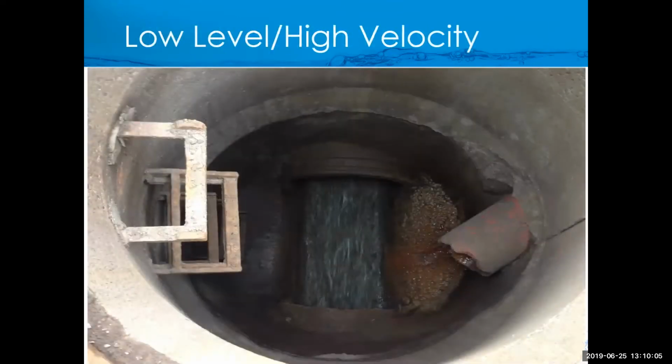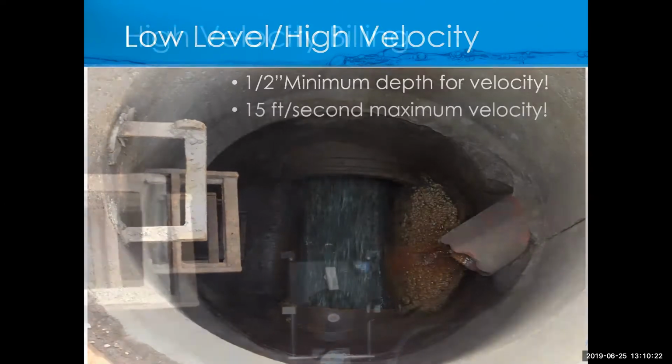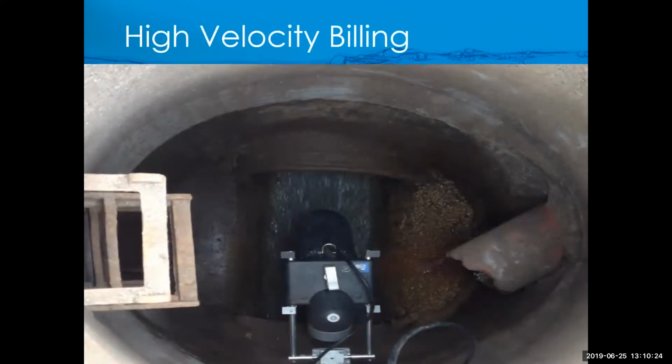Okay, so here's a shot I thought looked pretty good. This is a low-level, high-velocity application up in Minnesota. Their depth here was less than 1 inch, so they couldn't put a standard AV sensor in and get good results. The laser spec is a 1/2 inch for velocity, and we will read up to 15 feet per second. This shot right here gives you an idea of how the laser was installed. The laser can mount either direction. We don't care if it's pointing into the flow or away from the flow.